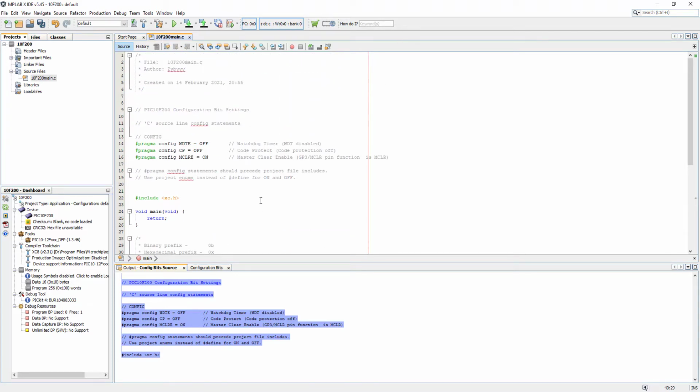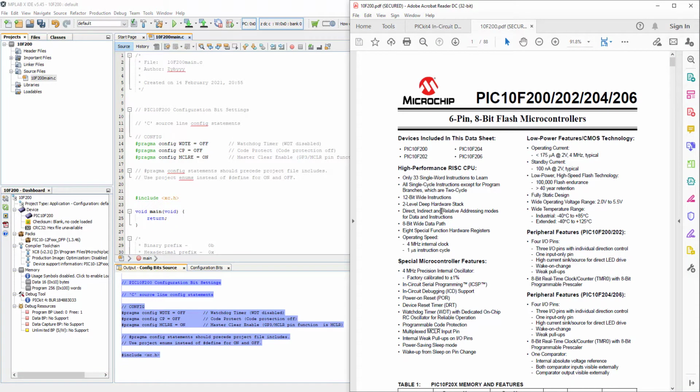Now before we can start with setting the pins high or low, we need to set the TRIS register, which means we have to give a direction to each individual pin. Very useful now is going to be the data sheet for our PIC microcontroller. I've got it here, you can download it for free from the Microchip website. So usually they carry a few devices in it. We've got here our one, 10F200. So what we are interested in here is PIC 10F200.